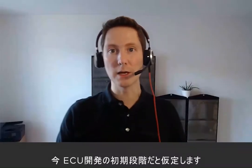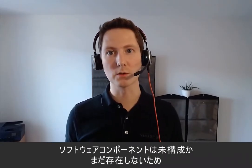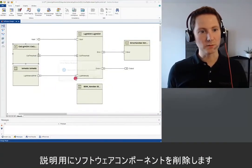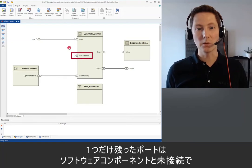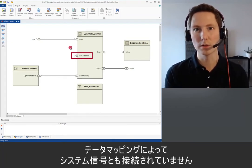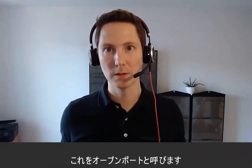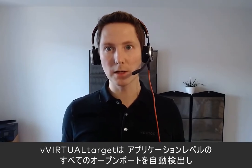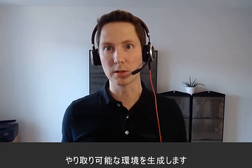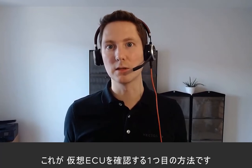And now let's imagine we are in an early development state of the ECU and maybe a software component is not ready configured or simply not there. So to illustrate that, let's remove that software component. And what is left is only one port, and this port is not connected anymore to a software component or to a system signal via data mapping. We call that an open port. And vVirtual Target detects automatically all the open ports on your application level and creates interaction possibilities for that. This is one way how you can take a look into your virtual ECU.